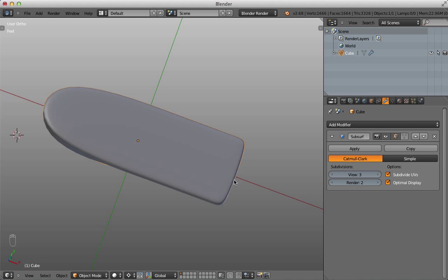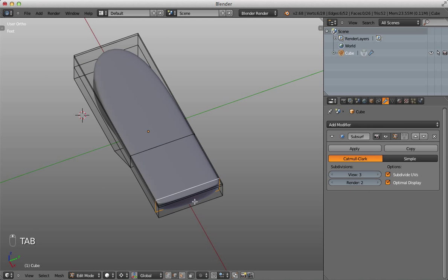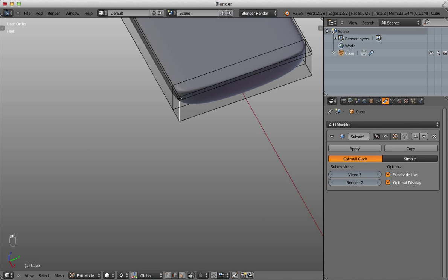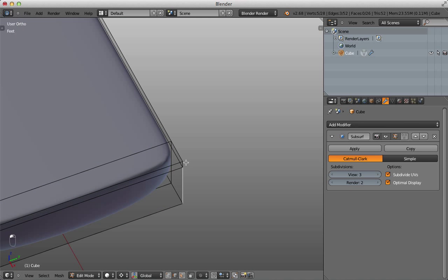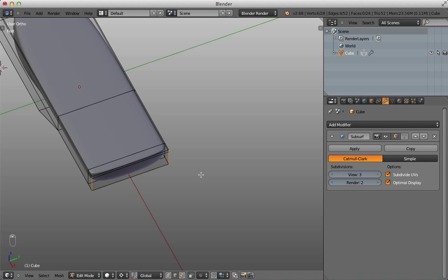Now this one is pretty flat, but maybe I would like to have a really small minimal arc on here. So I have nothing I could grab, so I have to add a little bit of geometry. Well, there are two ways how I could do this. I could, for example, select those points, press S, and then, hold on, make sure I have bounding box. I press S and Y, so I scale them along the Y-axis to each other.